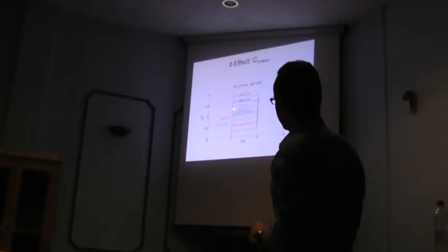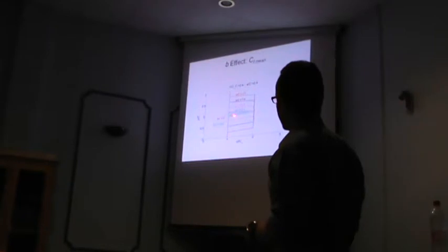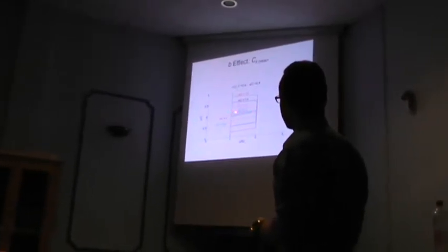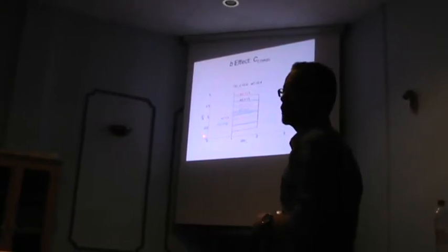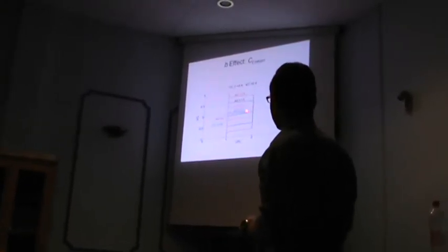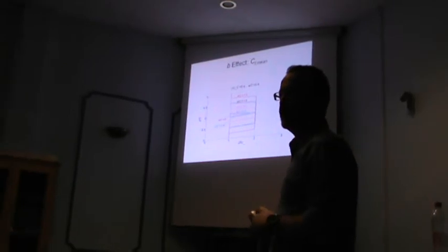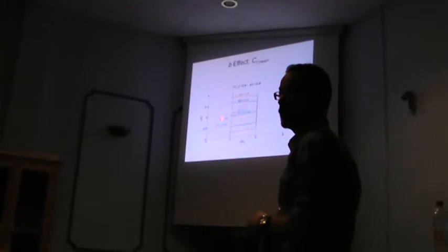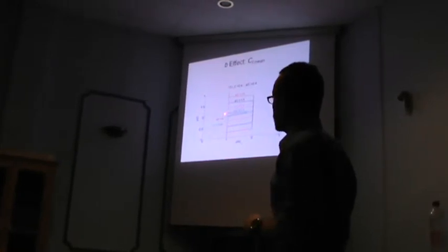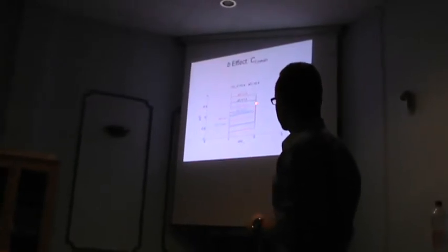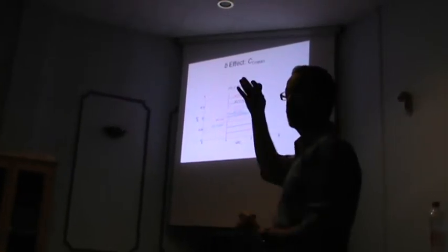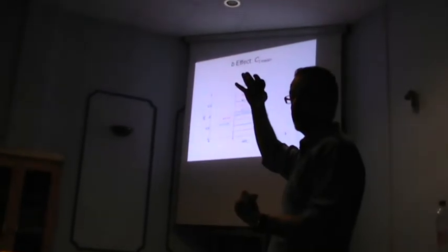As you increase the B, with the frequency the same, you actually start to develop this jet profile. And the bigger the B is, the jet becomes stronger as well as wider. Eventually, beyond a certain B, this profile becomes plug-like or slug-like flow. It's a top hat profile where the peak of the velocity does not change anymore, and instead the width of the profile keeps getting bigger and bigger.